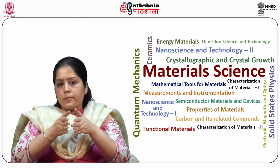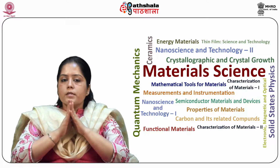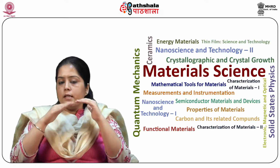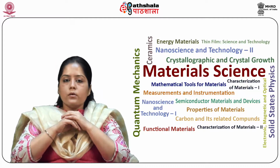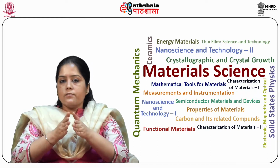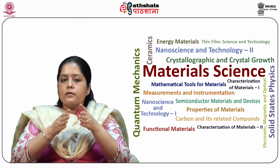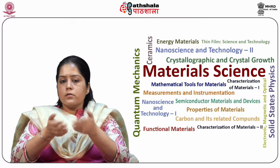The cost of the cell and concentration ratio decides which kind of solar cell will be used under concentrated solar radiation. For example, if the concentration ratio is less than 100, then there is no meaning of using the gallium arsenide solar cell, as the performance of silicon solar cell is also satisfactory in that case. However, if the concentration ratio is more than 100, then silicon solar cell should not be used and the only choice is of gallium arsenide solar cell.